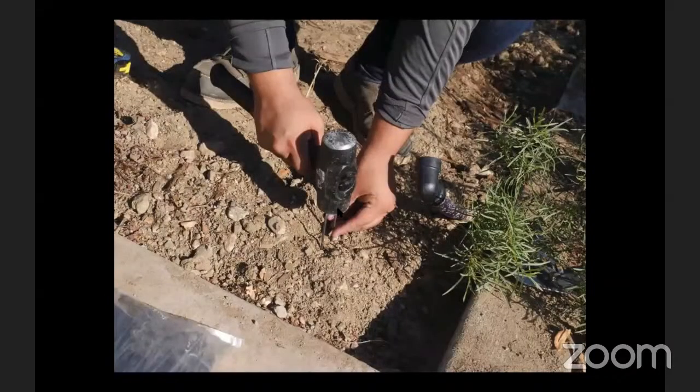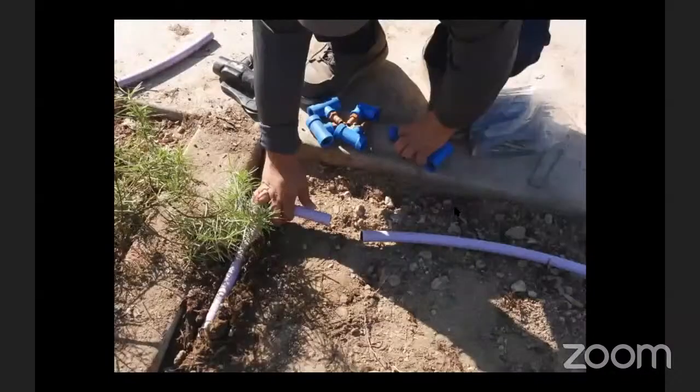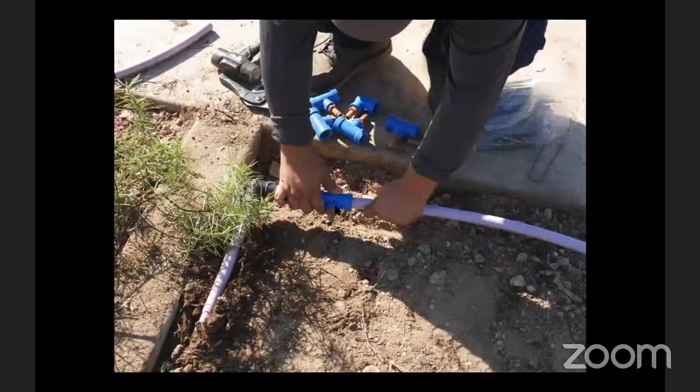And what I like to do is these are the little staples that are used to hold down the drip irrigation. Sometimes they're called jute staples. You can see one here. You buy them in a big bag. They're cheaper and you can get them in much larger bags if you go to the landscape supply store rather than Home Depot, and the quality is usually a little bit better. And so just cutting the line and installing the T at each one.